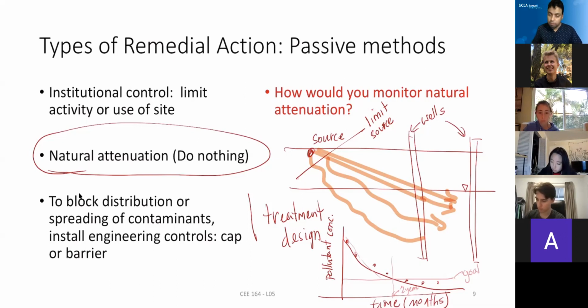So now for this natural attenuation to occur, what kind of engineering method do you need to learn? The only thing you can learn from here is how to make the wells, how to design those wells, where to place the well. Obviously, you are not going to learn how to make a groundwater well. It's basically putting a PVC pipe into the ground, that's all the groundwater well. Typically, they are 1 or 2 inch diameters, passing through the ground, and they can go as deep as needed.